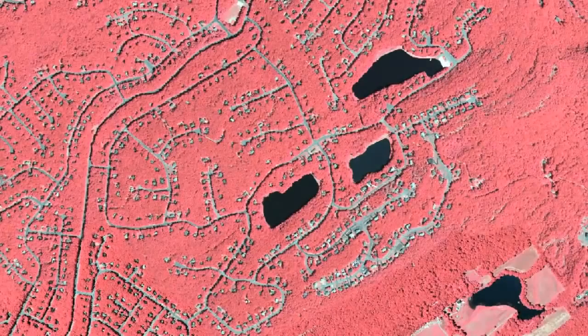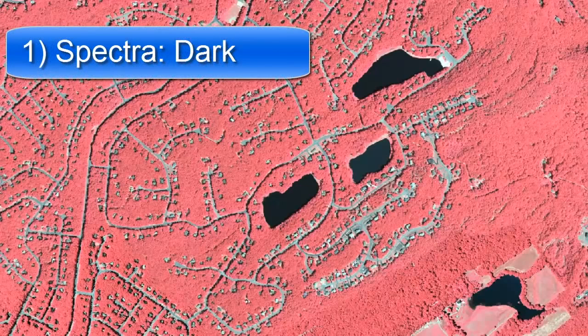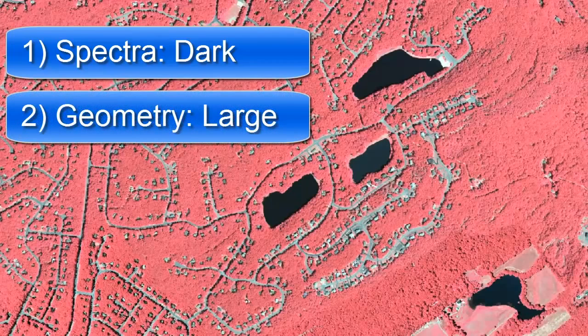For the example, we're going to extract water features from 4-band aerial imagery. This is high-resolution 1-meter aerial imagery. As you can see here, the water features are fairly distinct. Prior to building the rule set, we want to think what makes these water features stand out. Well, first of all, their spectral characteristics are that they're very dark. Second of all, their geometric characteristics are that they're quite large compared to other features in the scene.